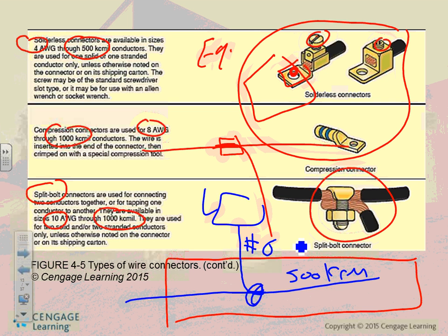They go thermal image. Now it's easy. They open it, the thermal image, it gets hot. You can see it's hot. When it's hot, it means it's expansion and contraction. It gets it loose a little bit. So you shut down at the predetermined location. You go torque them, get the tape out, re-torque them, put them back, maybe change the lugs. That's called maintenance. Because everything is like your car and mine. You buy it brand new, and if you don't maintain it, it goes down the drain.